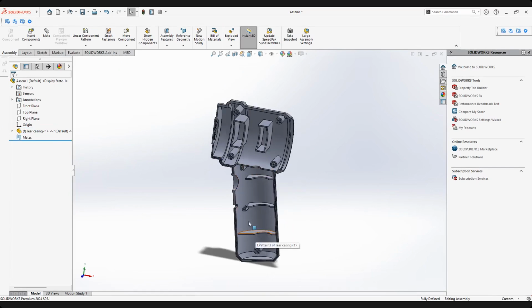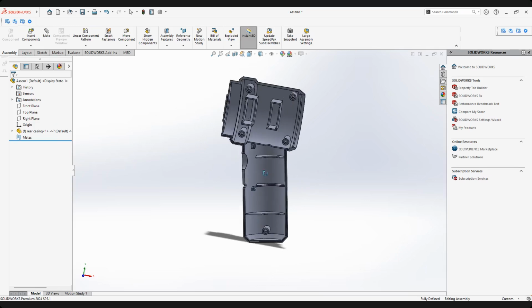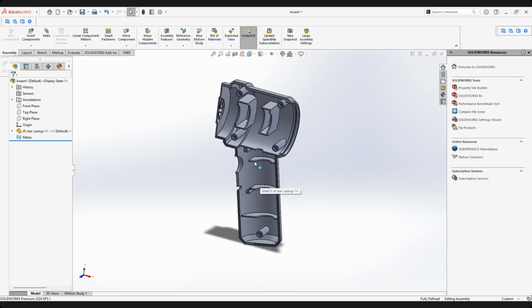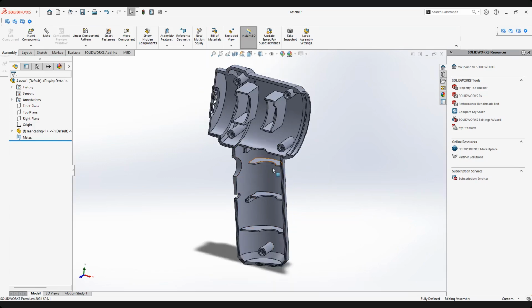Yeah, imagine you want to assemble this thing back. Because where you are doing this, in industry, in the manufacturing line, the last line of production is the assembly worker. You need to assemble your parts. All the parts are already on his table, on his platform, to do assembly. So you have to provide an assembly exploded view drawing to show them, so they will get it. You will point the balloons: part number one, part number two. You cannot randomly name them. The base will be part number one. So for part number two, I want to insert this one. What is part number two?